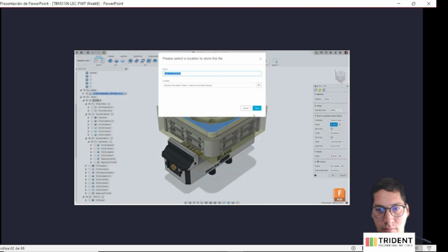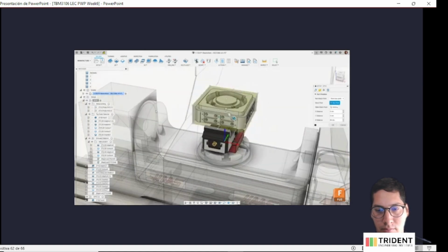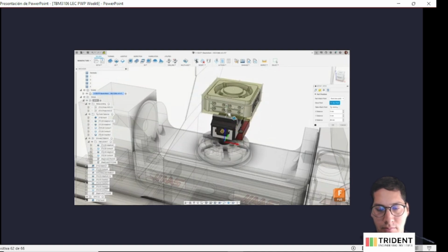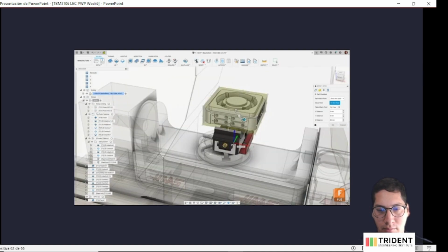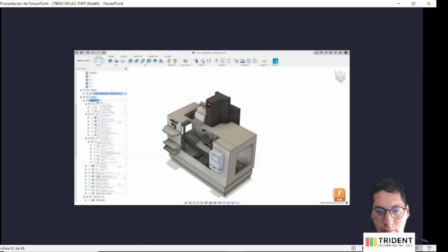Once downloaded, the machine is automatically selected and the Part Positioning tab will now become available. Clicking the Part Positioning tab defines the location of the part attachment, alongside where that part attachment connects to the table. Further offsets can be applied to fine-tune the location required. Now that we have imported the machine and positioned the part, it's time to simulate. Machine simulation is available when simulating from both setup level as well as from the individual toolpath.